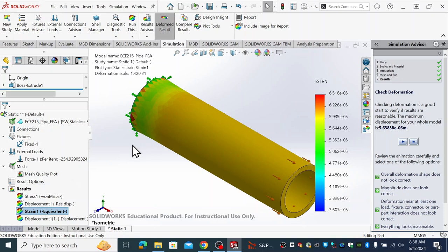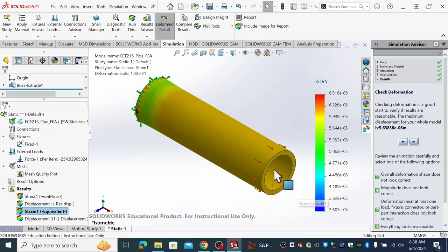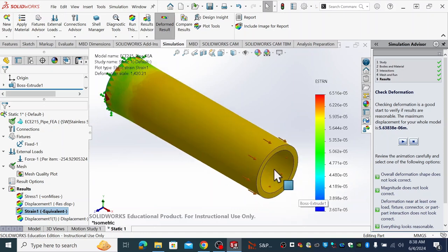You can run the study definitely with something well larger. That will make a little more sense. So I hope that helps. Let me know if you have questions. You are welcome to make different loads, to have loads in different directions, having some connections that are different, so two different surfaces connected, either fixed, or with pin connections. Just make sure that it cannot move. Okay, you have enough connections to make it stay static.